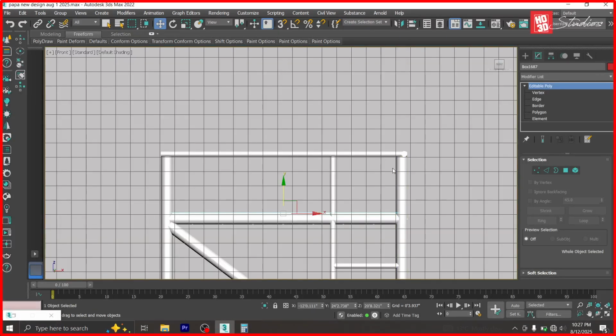Now, what am I trying to do? The job of a balustrade, when you're on a platform, say a balcony or on a staircase, is to prevent you from falling. The recommended height is not less than 3 feet, but 3.5 feet is often recommended.